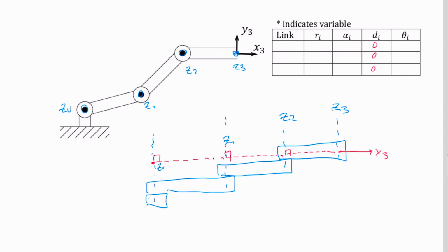So let's build this out. I've got to set my base frame. Again, I'll pick it conveniently. So I've got my X0 there, coming through there. I've got my origins that I'm going to place on each of these points the same heights. And so then my Z1 axis has to intersect both Z1 and Z0. Since they are parallel, then I can pick it at any height, but I've picked my points here. And so if I go from here, I dot line until I get to this origin, and then I continue that on. That is my X1.